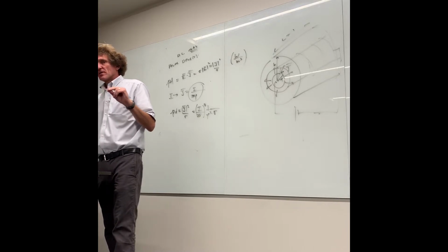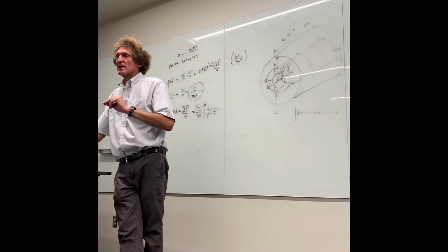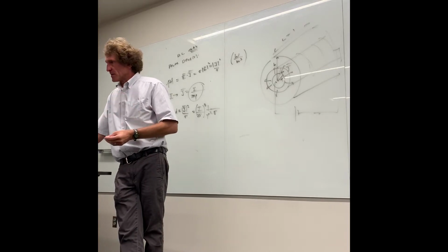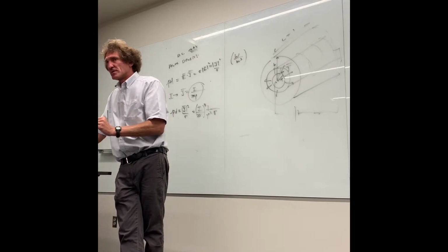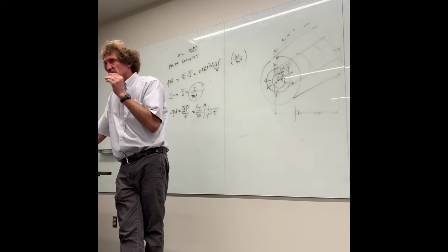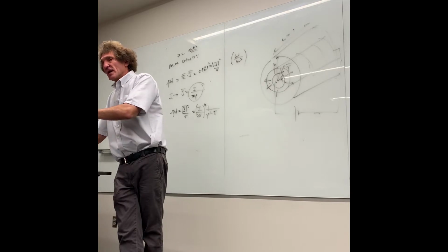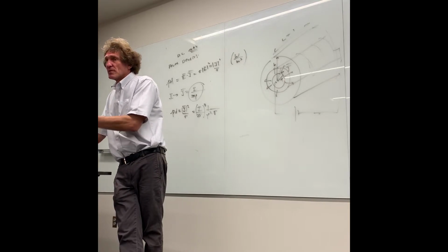Most of the time when you think of electrical engineering, how a thing fails, you think about something arcing through a silicon dioxide dielectric. That's how MOSFETs fail all the time. But it's not just that. When you have single thin wires that all of a sudden experience a fairly large current, say with lightning hits, it induces a voltage, it induces a current. That current, even though it's only there for a millisecond or less, may be enough to heat that wire to a point that it melts like a fuse.